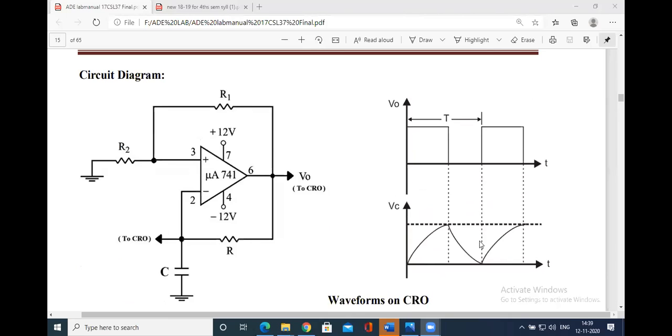And this is the waveform that we need to get. This is called a single time period. Starting from here to here, how do you measure? Basically, this starts from here, it reaches the peak and drops over here. So this complete cycle, you could see my mouse pointer, it has reached the peak, that is 50%, right? Once it reaches, it again goes back, comes down. So from here to here, the complete cycle is called a time period. We need to calculate this complete time period, and from that we need to calculate the frequency. That is what the experiment is all about.